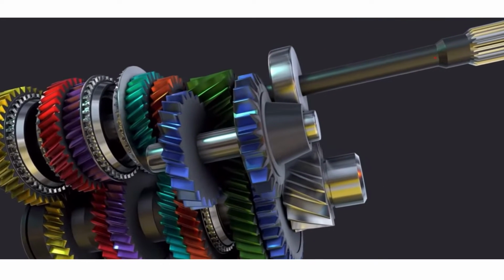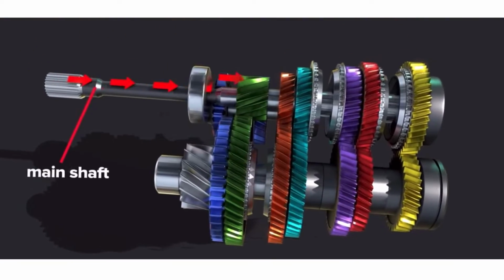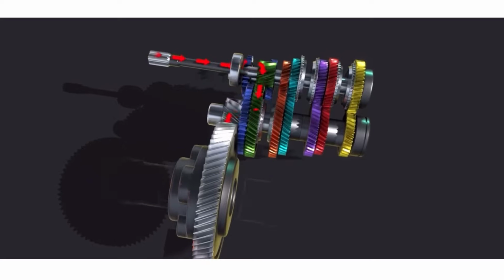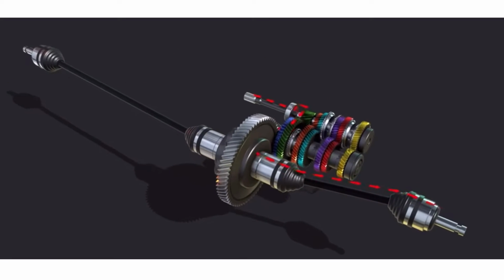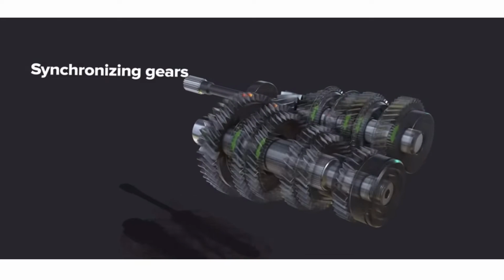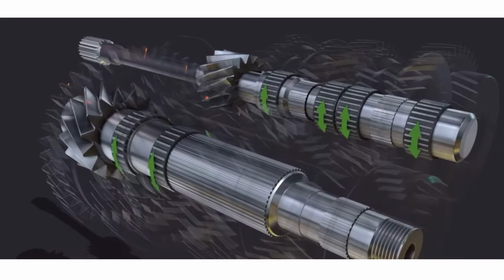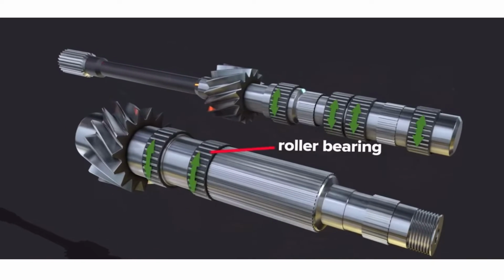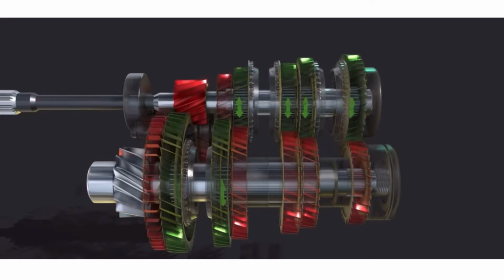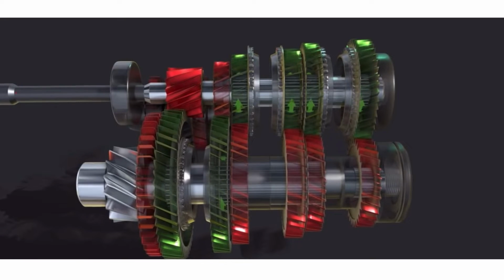Those are: 1. Spur gear. Used in all sliding mesh gearboxes, these types of gears have straight cut teeth. 2. Helical gear. They are the modified version of the latter as they have angular cut teeth. 3. Bevel. They are best of all above gears having a conical cross-sectional area with angular cut teeth. 4. Idler gear. It is the small gear used as a reverse gear, usually mounted over the lay shaft.